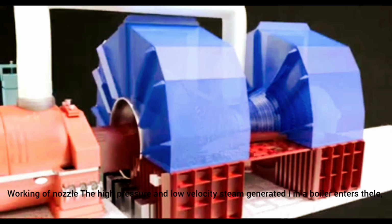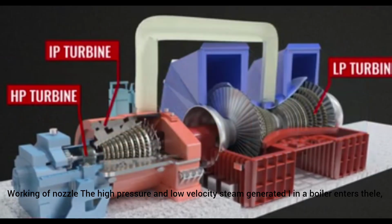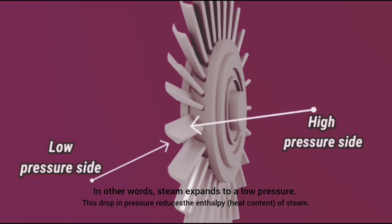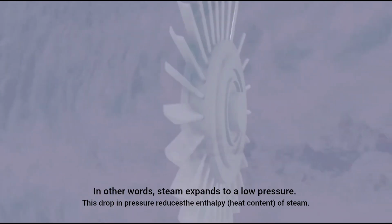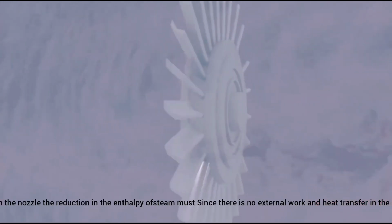Working of a nozzle. The high pressure and low velocity steam generated in a boiler enters the nozzle, and as it passes between the entry and the throat, the pressure of the steam drops to a low value. In other words, steam expands to a low pressure. This drop in pressure reduces the enthalpy or heat content of steam.